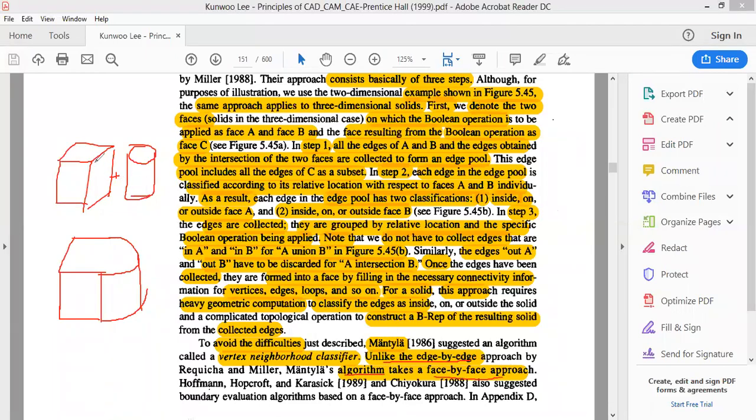What are the common faces if we have to add, and which is the common face that is going to come into picture if we are going to subtract? Which are those common features, whether the faces are inside or outside? Like that, face representation data are taken and the Boolean operations are performed in solid modeling. So the only change in the algorithm is that from edge by edge, it is changed to a face by face approach for solid modeling.